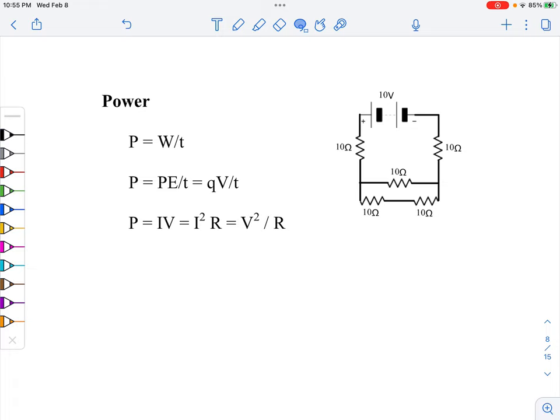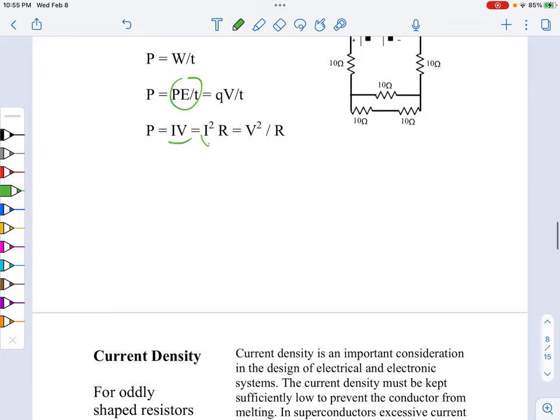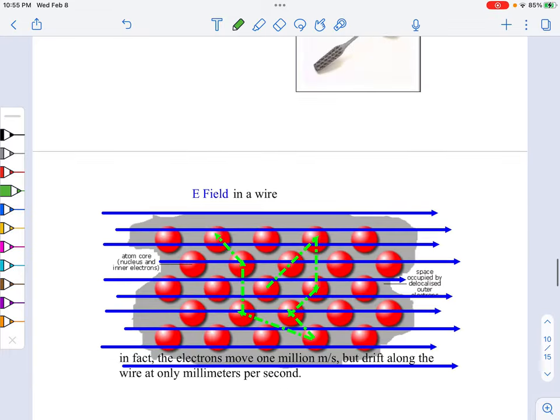And so what we do is we send that electricity at extremely high voltage to keep the current down. Here's the relationship: we're going to transmit some amount of energy per time. For the same energy per time, for the same power transmission, a really high voltage yields a lower current. And a lower current means you're going to get less overall heat generated in the wires, because it's that current pushing through the wires that ultimately generates that thermal energy. So that's a fun fact. Why does that happen? Well, it has to do with this. I'm kind of skipping around here.